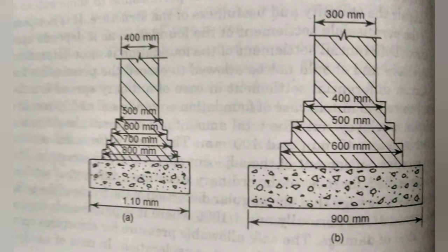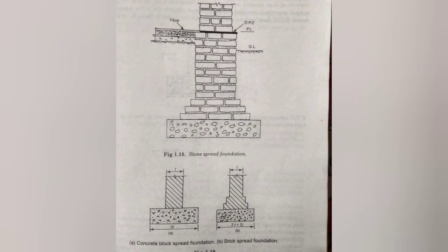What is wall footing? In this type of foundation, courses of brick below the superstructure wall are laid by giving a 50 mm outward offset on either side of the wall. The depth of each course is normally 100 mm. However, in some cases, the thickness of the masonry may be two courses of 100 mm each in each step of the footing. The concrete bed performs many of the following things.